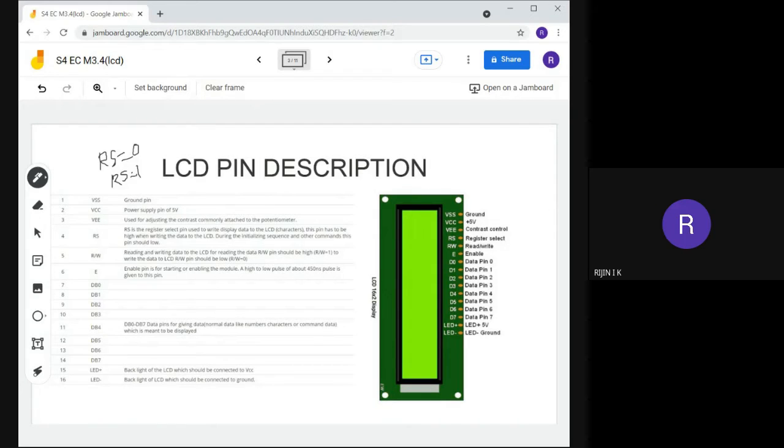Then another pin is the RW pin. For reading and writing, we use this pin. To read data, we set the RW pin equal to 1. RW equal to 1 is for reading data. To write data, we just set the RW pin equal to 0. So that is the use of the RW pin.